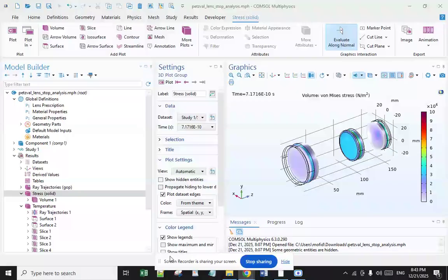And what about the optical analysis? Next, the analysis returns to ANSYS CODE V for the optical analysis. This process mirrors the analysis performed to derive the initial spot size diagram pre-STOP analysis. However, the geometry is now updated to reflect the deformed state of the optical payload. In turn, the following spot size diagram is computed.